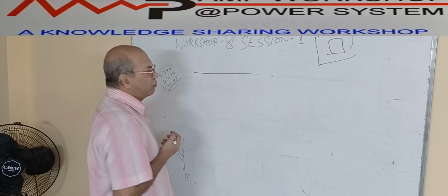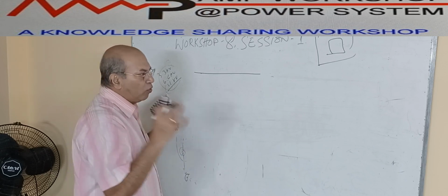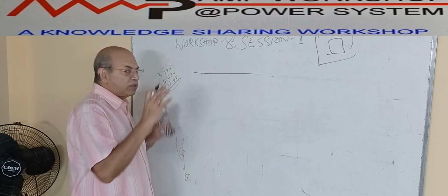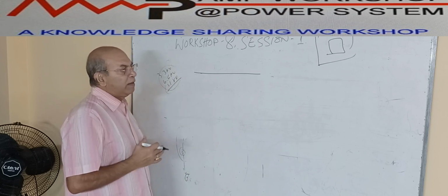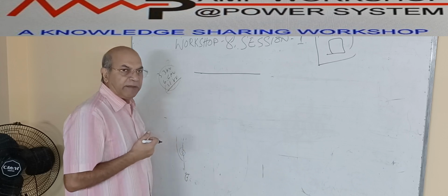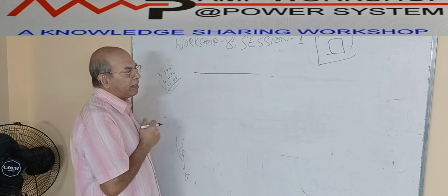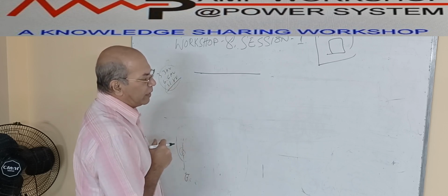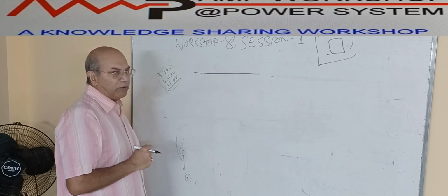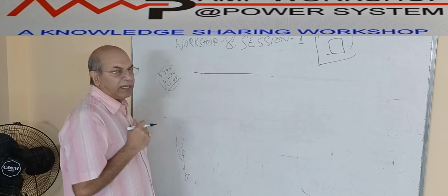It is a gas insulated switchgear. All the busbar and the power components are enclosed inside SF6 gas pressure. SF6 gas is enclosed inside a container, an enclosure, and that is pressurized and sealed. From there the gas cannot escape. There is a monitoring arrangement for the gas pressure, like our normal cylinder gas pressure. Within that gas environment all these power components are located, and those components are permanently fixed. That is what we call GIS switchgear.